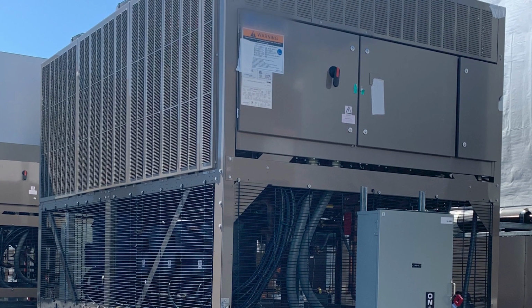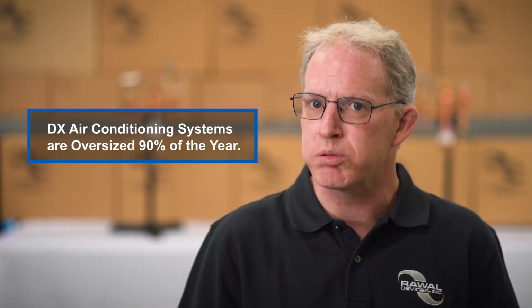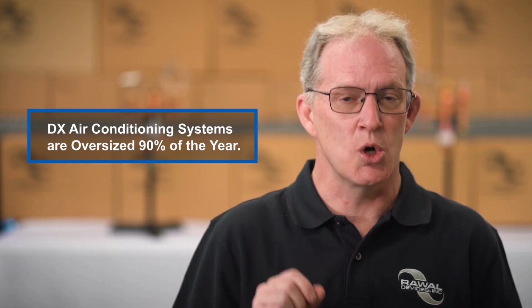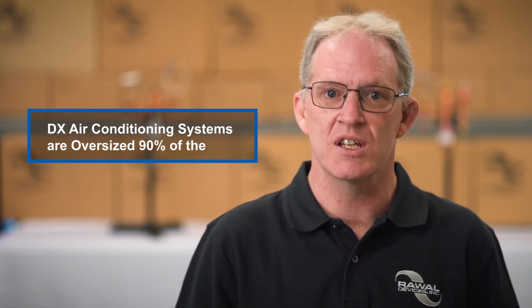to the lack of design day conditions. Design day conditions are the hottest day of the year and the highest indoor heat load that the unit expects to see during the year. The reality is conditions change day to day. These design day conditions only happen about 10% of the time. That means that 90% of the time, your properly designed air conditioner is oversized for the current conditions of the